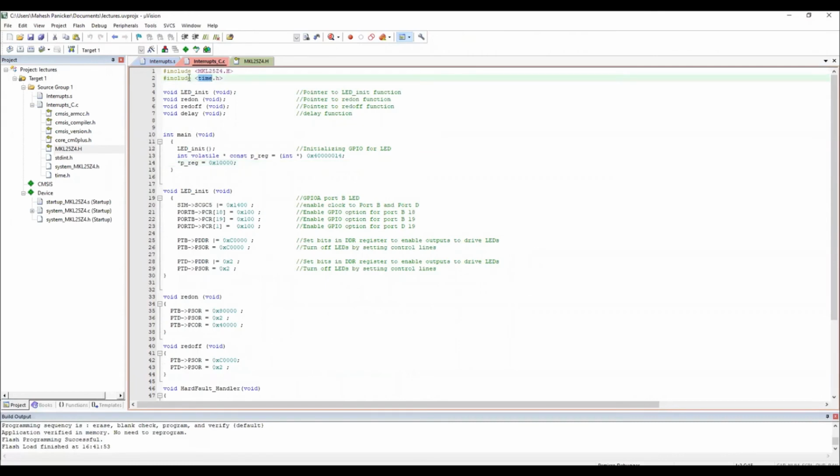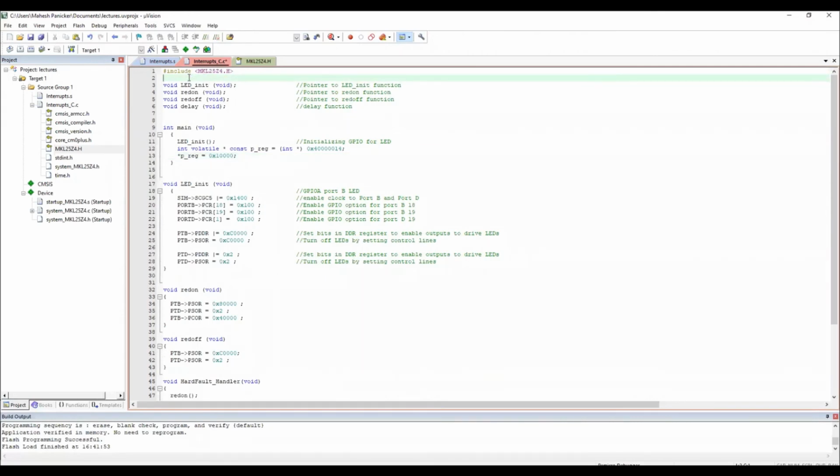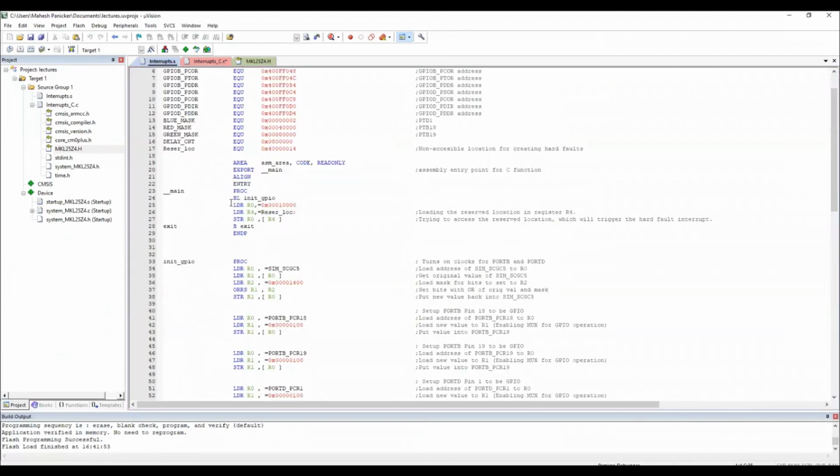Then this is something like the export. Whatever you are declaring below, you have to declare at this point. And you can actually copy everything and put it as an interrupt c.h file, put all these files there, and then include that here. That is what people typically do with header files. You can create a separate header file and put all these in there. That's going further.